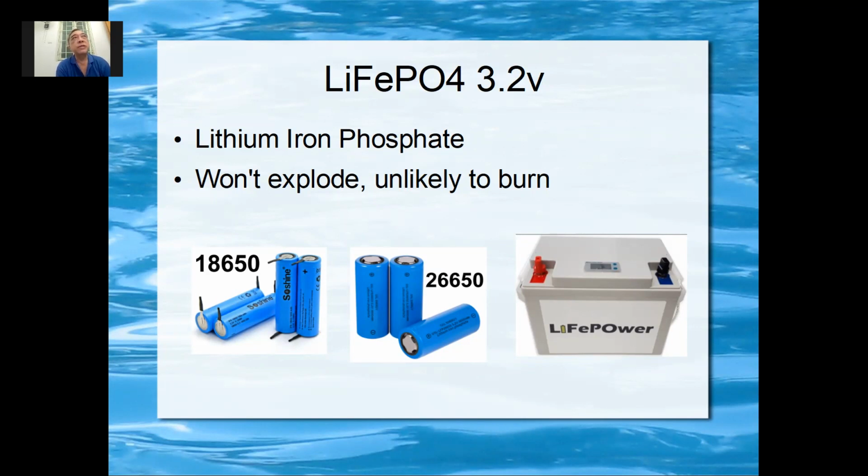Lithium batteries are not supposed to be connected in series. But if you want to connect them in series, you can just connect them in series to use it. You cannot connect them in series to charge. You will have problem. So if you need 48 volt, you cannot connect 4 of these lithium battery packs, 12 volt each, put them together in series and charge.